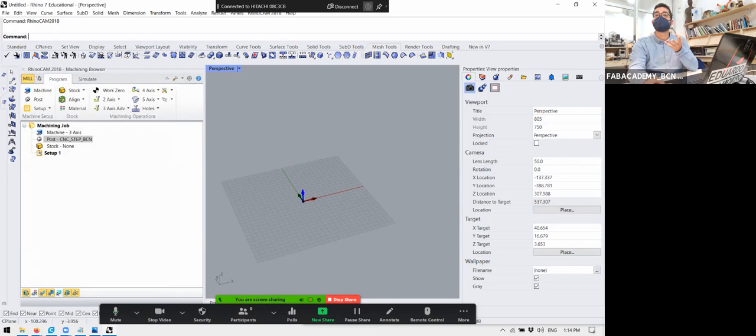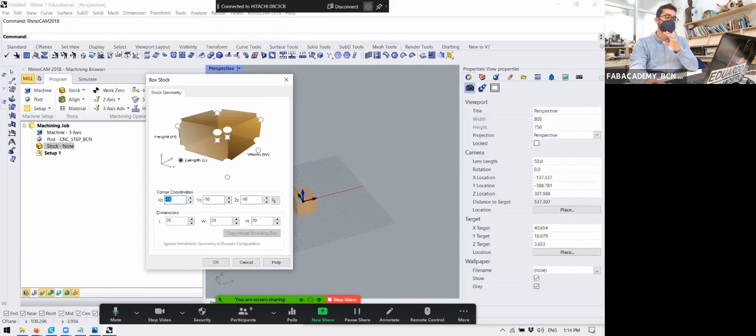Then we choose the material. What material are we going to cut? Let's double click, and we need to set up. I don't know why, but it says the origin is always at 0. We want to have the origin of the material at 0. Let's choose the maximum. A full board of material is usually not what we get here, but in states like Korea, Japan, all over the world, in general, this is the standard full-size dimension.